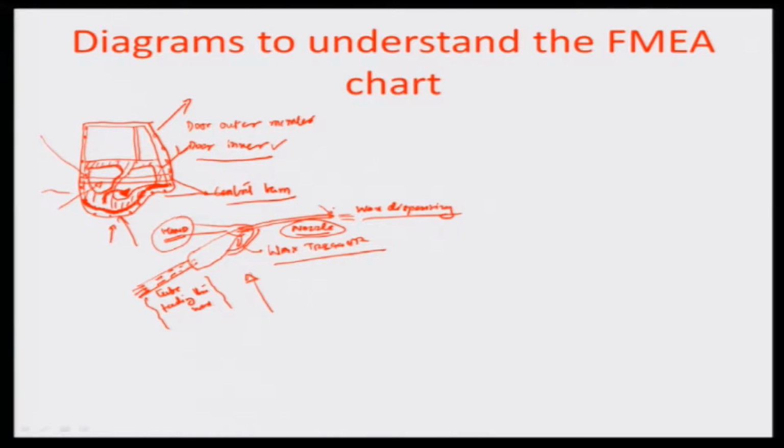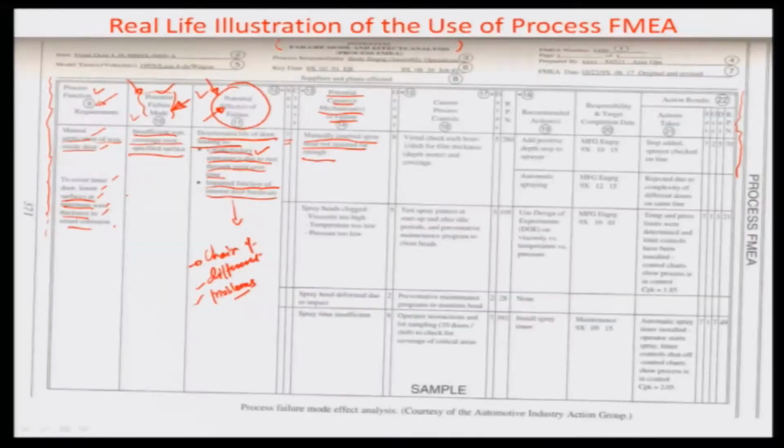So you have to consider the difficulty level, that this nozzle actually needs to get inserted into this small space here, and the nozzle has to again be turned from this side to this side, so that the complete coverage on this particular region happens. So it is a very, very difficult proposition. So that is one part of it, that is manually inserting the spray head, and during that you feel that the spray head is not inserted far enough, because probably the nozzle is not able to cover the whole area which needs to be coated by this particular nozzle.